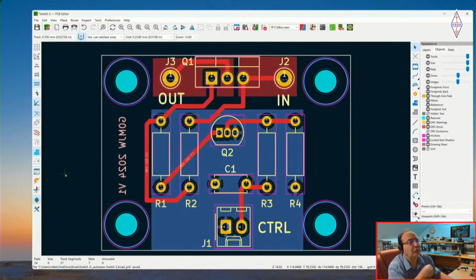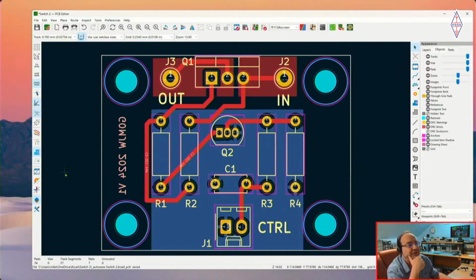And the reason those weren't automatically in 1 millimeter spacings was because the grid size that I'm using is imperial rather than metric for placing the components. And again, you can place the components on a metric grid, but if you do that, a lot of components are actually imperially spaced, so it makes wiring them up more difficult. Absolutely. I mean, the pitch, as we call it, the difference between connectors, for example, is still 0.1 of an inch, or made up of a multiple of that.